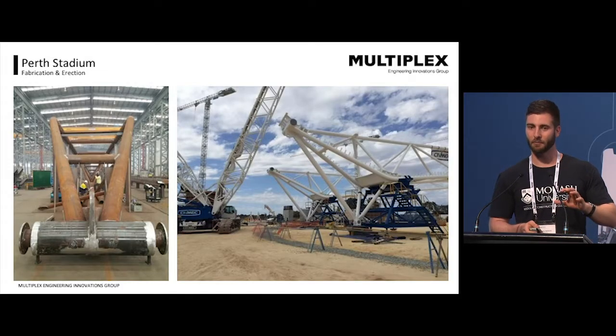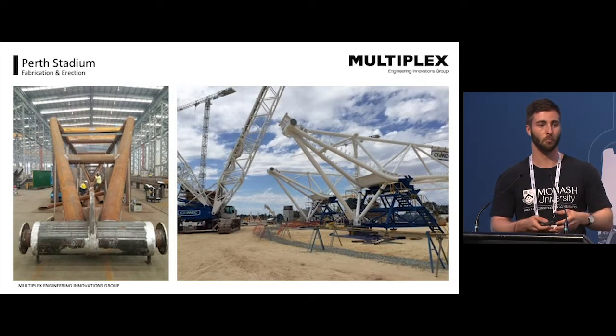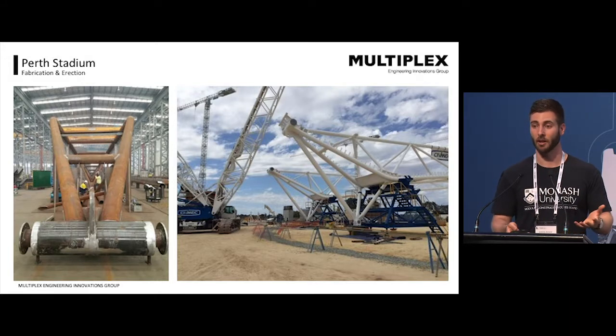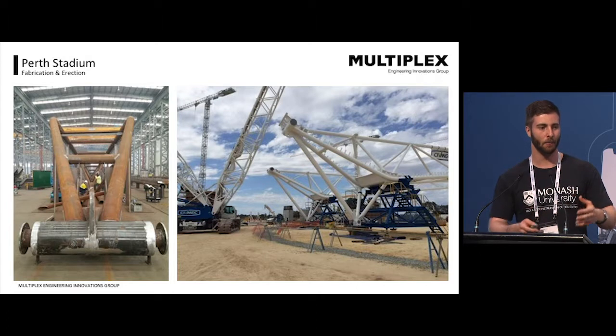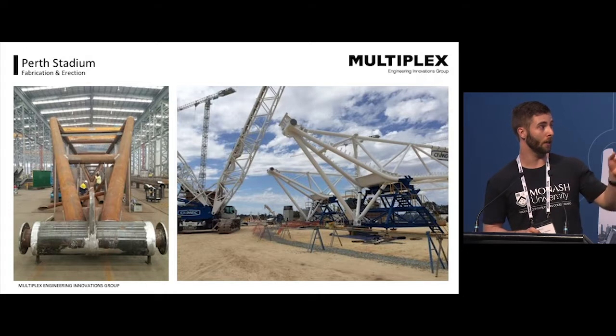And it's not something that you'd potentially think of as actually being modular, but the roof trusses themselves were all prefabricated up in these huge elements, which are effectively just a big modular section. They're then transported to site on customised rigs, which basically get along on the back of a truck. So all designed in with that fabrication and with the delivery in mind. And then, like I was saying, on site, we've actually installed those 3 members which hold up the roof truss while we're on the ground. So we basically just lift that up, and it's quite a simple installation from there. We're bolting a plate to the column.